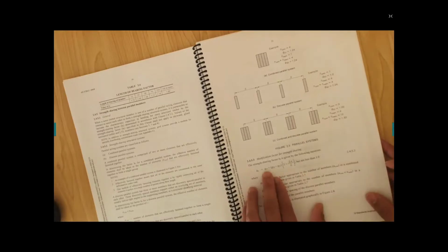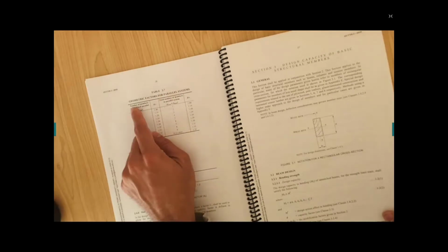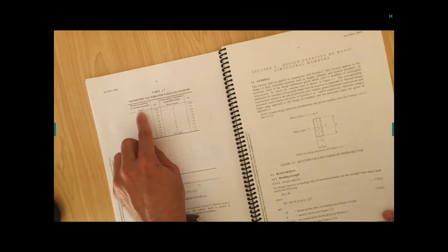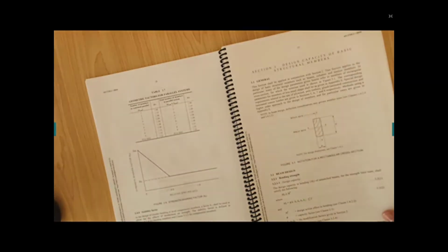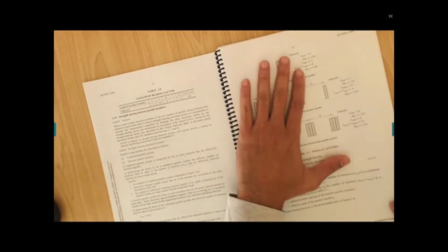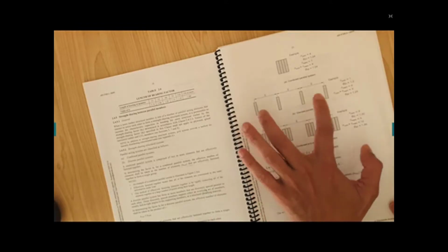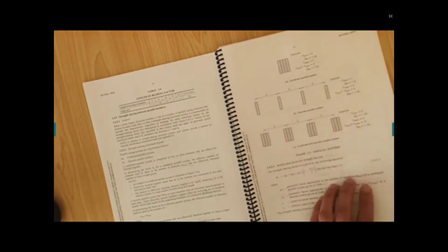We need to get G31 and G32 from table 2.7, geometric factor for parallel systems. So we will have a number of combined beams, and we're going to get a total number of members in parallel systems and combinations times the number of members. First of all, let's calculate n com, and they have given you figures for this kind of system. By looking at our figures, it looks like we have a B system, discrete parallel systems.